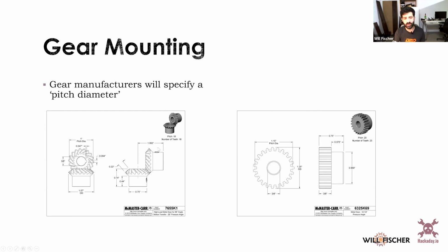If I'm doing bevel gears, you'll notice that it shows from the gear throat down here to the center of rotation here. And if I look on this gear as well, so they're showing two of the same gear, then it would be the same the other direction. But I may want to be using this to drive a different system. So if I have a different gear ratio with different numbers of teeth, then I would use those schematics respectively.